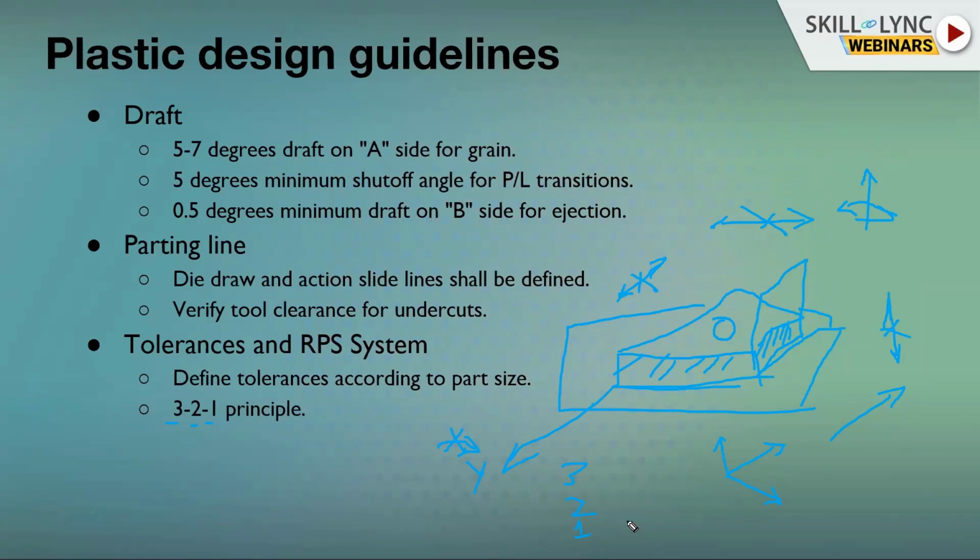And then we use this in plastics in defining the features, how to fix the plastic part using this 3-2-1 principle, using the snapping features or some attachment features. So these are the importance of the 3-2-1 principle.